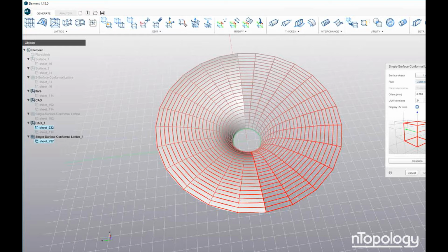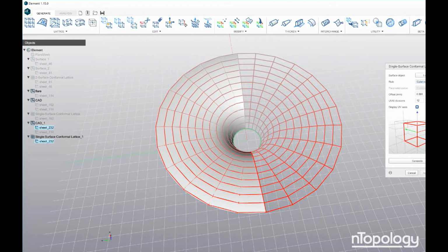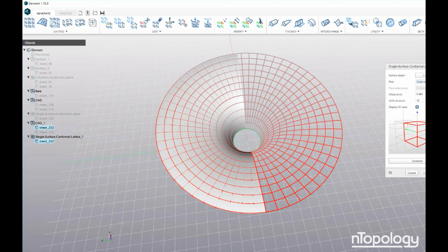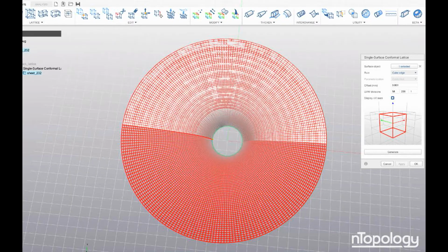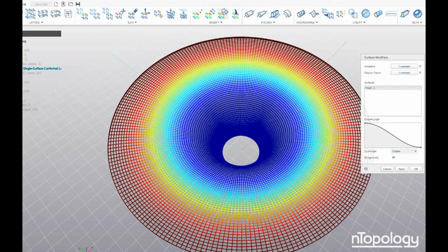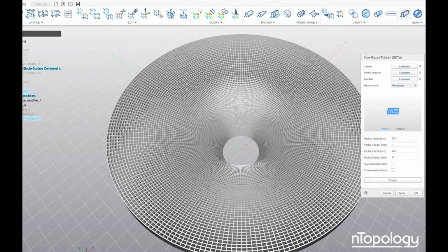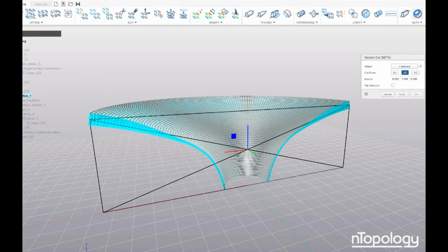And again, this is our conformal structure module. You can change the size based on the parametrization to have different sizes of ribs. You can have lots of ribs. And then for thickness, again, you could use a modifier, right? So you can use the distance to the edge. Maybe you want these ribs to be much thicker closer to the edge. And you can drive parameters of parts of the geometry with these distance fields, et cetera.